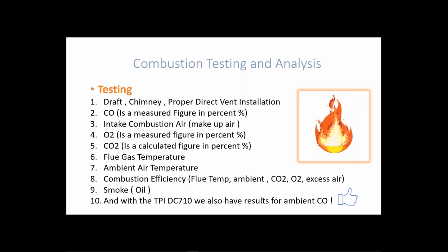Combustion efficiency. You notice I kind of put that pretty low down on the list. I understand that we're all looking for the highest efficiency so we can go back to the customers and show them that printout and show them how well they're doing efficiency-wise. But keep in mind, we will trade off an efficiency point or two for safety. We will always do that. I've never heard of a manufacturer that won't want you to do that. They all want you to be safe.